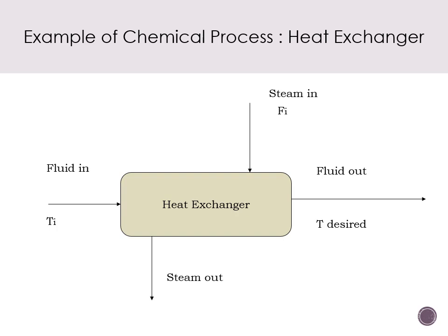The term feedback derives from the fact that the control variable is measured and this measurement is fed back to reposition the steam valve. This causes the signal variation to move around the loop. This loop structure is what makes feedback control simultaneously simple and effective. When properly tuned, the feedback controller can maintain the control variable at or near the set point in the presence of any disturbance, such as process flow and inlet temperature, without knowledge of what the disturbance is or of its magnitude.